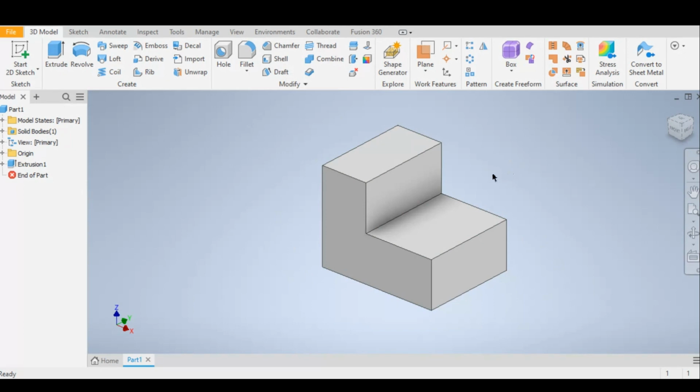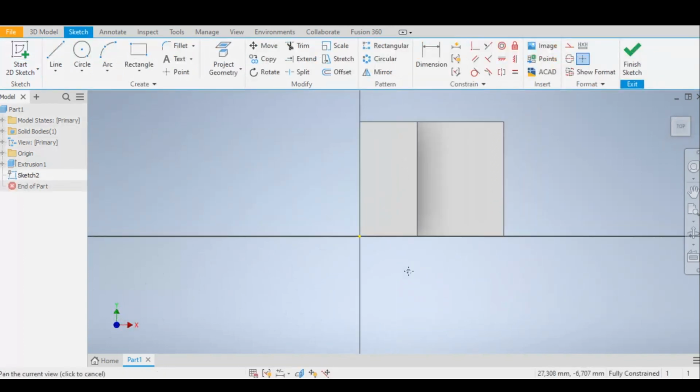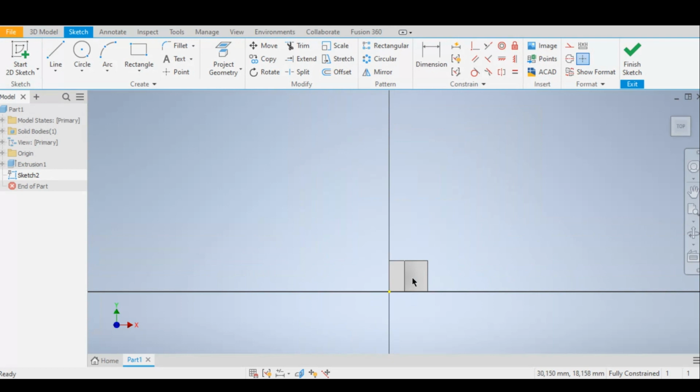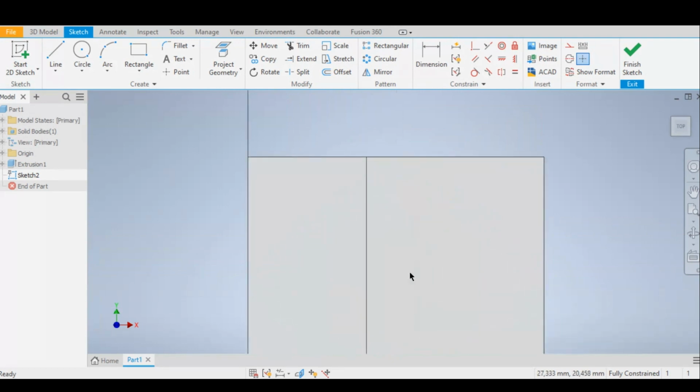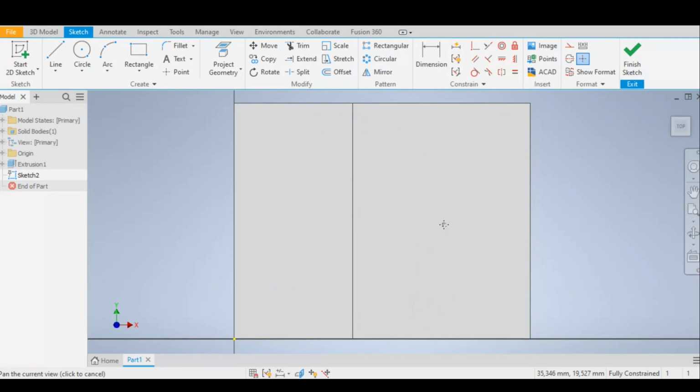So to include some cutouts onto this option here, we are going to simply head to the 2D sketch, start a 2D sketch, and once you select this option, you can see once I drag over our part, you can then start to draw anything on this surface that is highlighted. So let's do our first drawing on this surface. See, once you click there, it rotates automatically to this section where you can then start your drawing. Let's just get that back in picture.